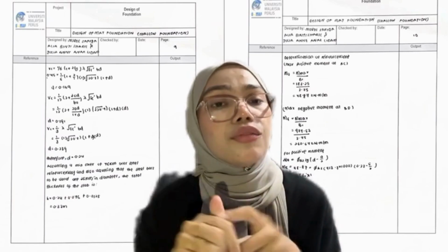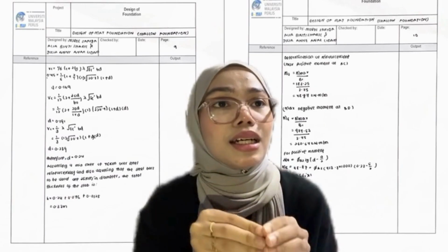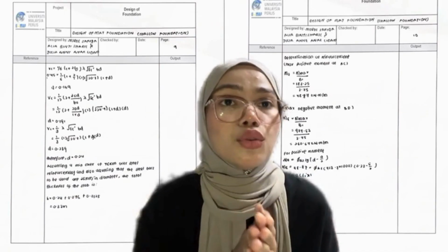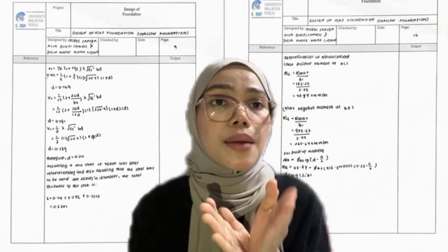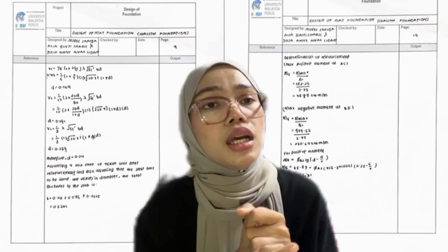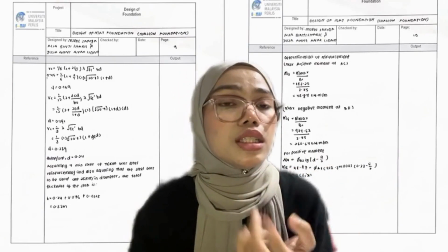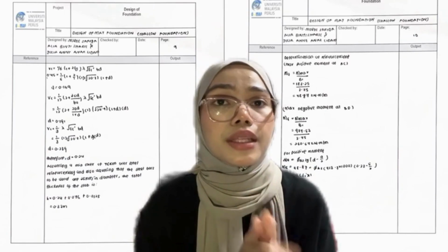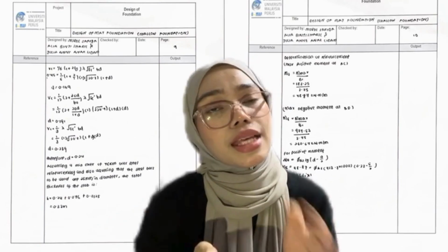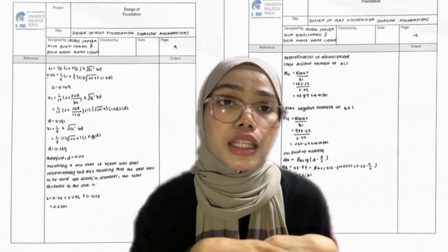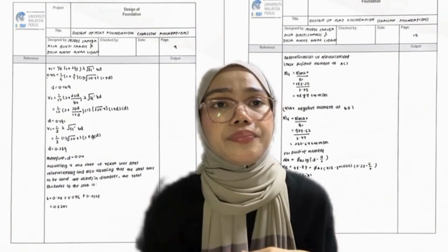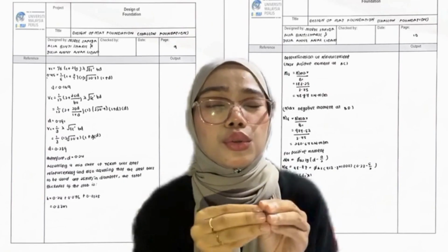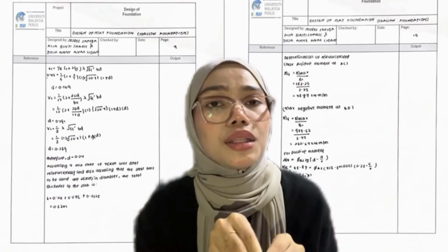First we calculate for the positive moment at AC. We need to calculate Mu, where the formula is M max divided by B1. So the total is 48.87 kilonewton meter per meter. Second, we calculate the maximum negative moment at BD. Mu is equal to 260.67